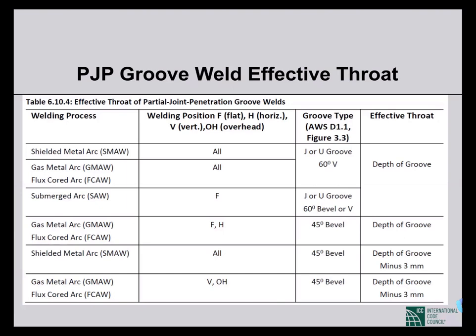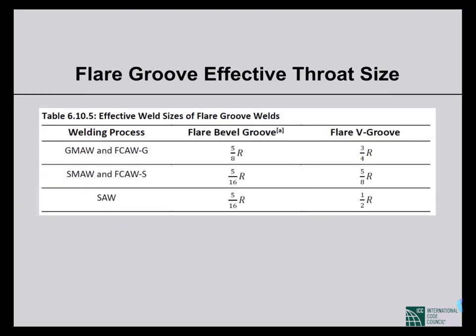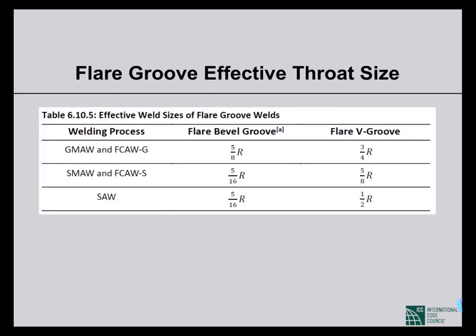So we need to consult this table to calculate effective throat. Now, for flare bevel groove and flare V groove, there is another table. Depending on the radius of flaring, we can calculate the effective throat size, the effective weld size, that is effective throat.